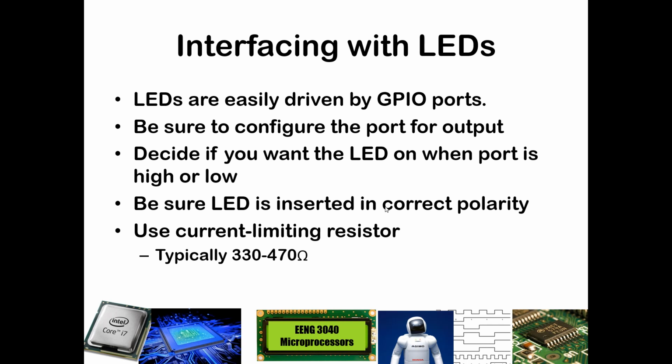And so oftentimes devices just have a little LED to indicate that there's power received to them or not. And so when we're interfacing with these LEDs, we want to make sure that we configure the port for output. We want to be able to drive the LED. LEDs are not going to give us a signal on their own effort. We want to control them. We want to determine when those LEDs are on or off. And that way you get to decide whether you're outputting a high or low. So making things an output means you, the user, in your software that you define, allow that LED to turn on or off.